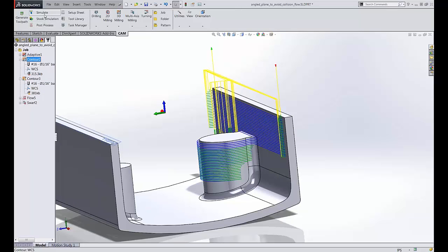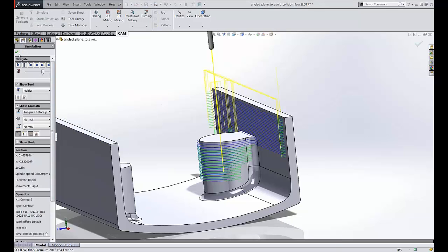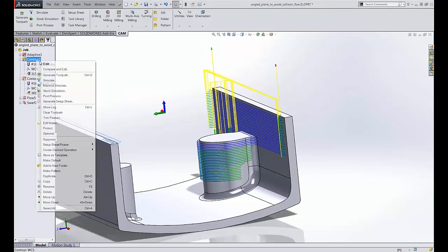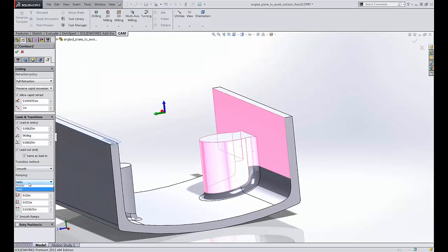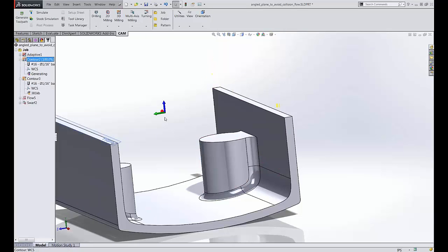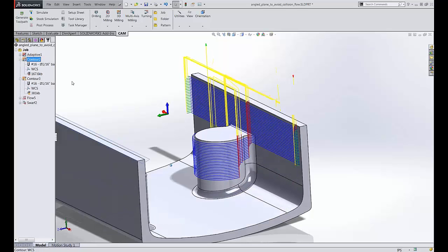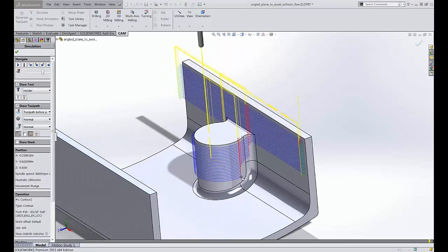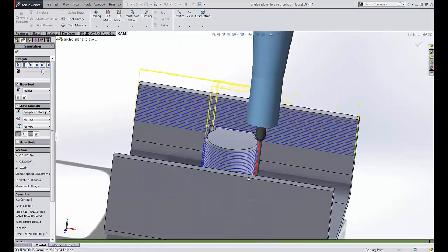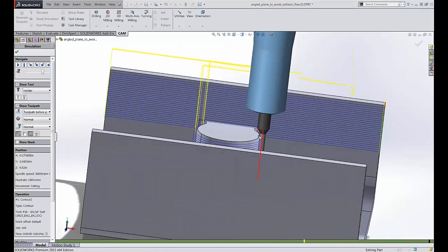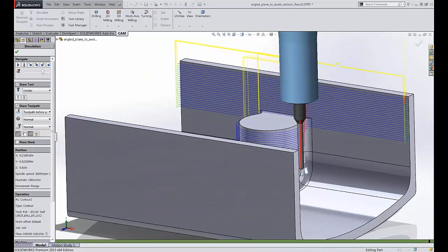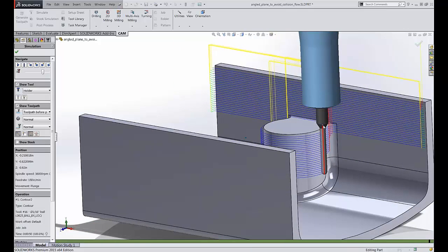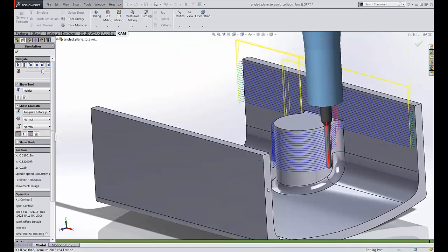So we've got a toolpath that's generated. I probably would want to tweak some settings real quick. Yeah, that trim feature is a good feature that I probably don't see used enough. That's a good example of it. You can see here it's being trimmed as it gets too close to the shaft and holder. That's clearly the last level that it can do before it would start having some collision. So it's just getting rid of the extra passes.